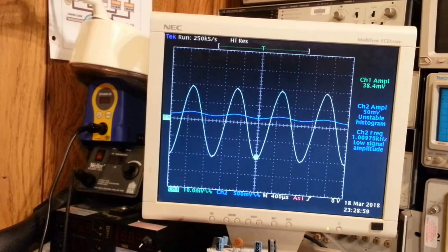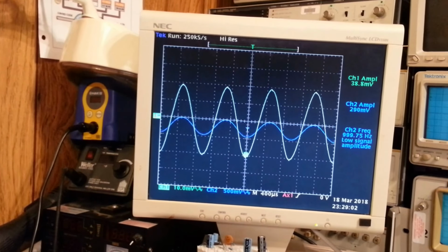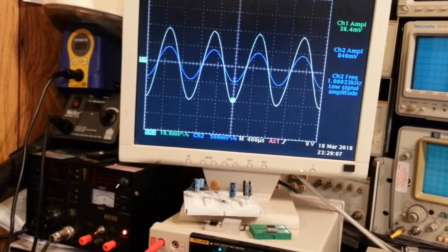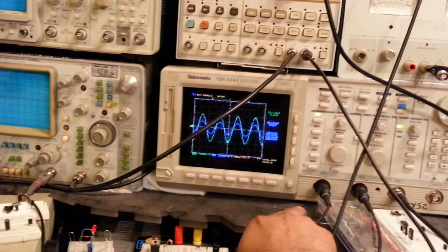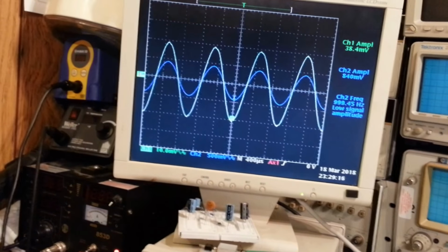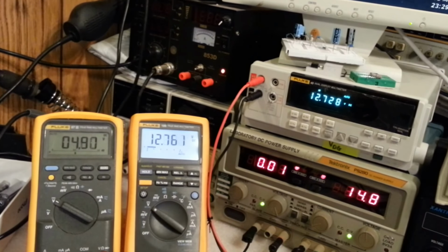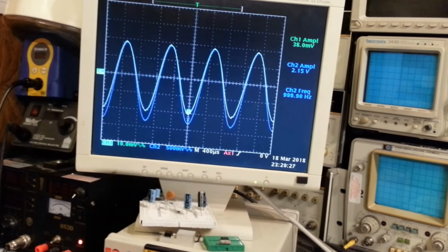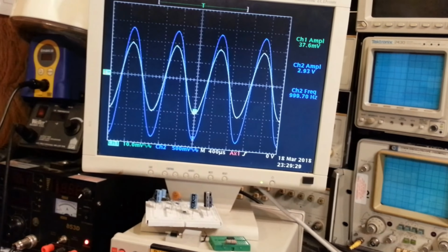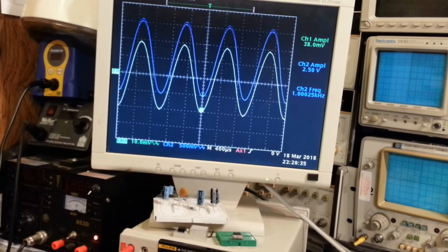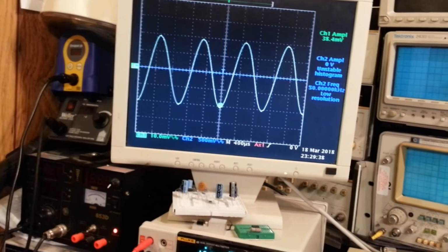The reason you see the thing shift up a bit is because of the scope input where I'm measuring. It's AC coupled, and because it's AC coupled, the capacitor is charging up because of the quiescent shift, right? As you can see, because of the current changes, the quiescent point gets changed, and it affects the quiescent point. But as you can see, I can vary it. So this is the maximum gain we get and minimum gain.